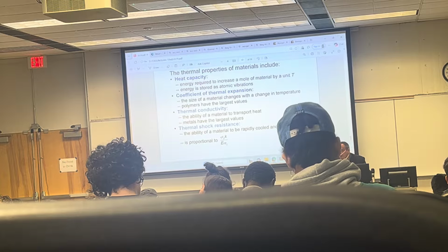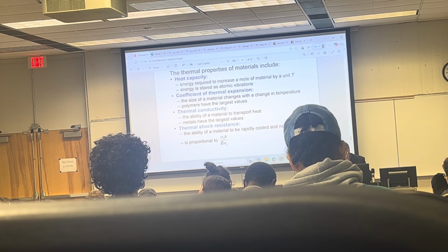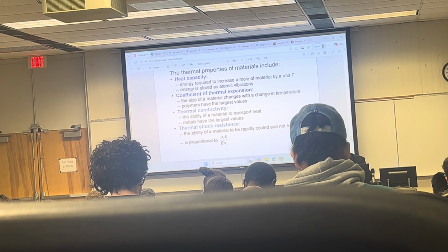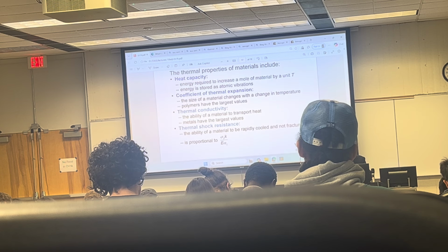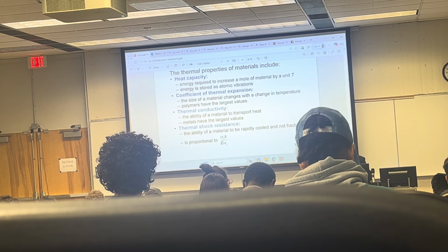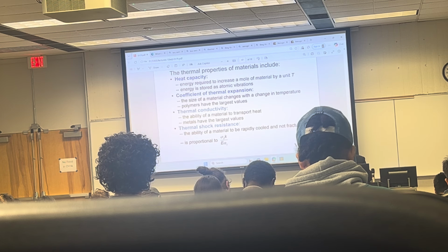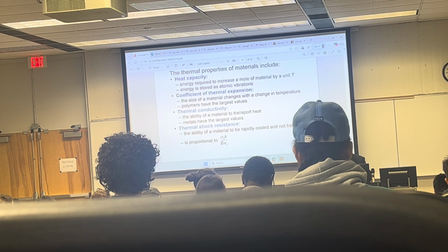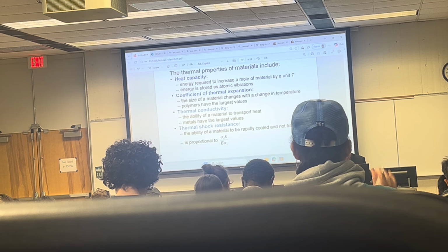Solidification happens by nucleation and growth, right? If the nucleus is less than a certain diameter, it's going to get redissolved due to the surface energy trying to collapse it, or it will grow due to the decrease of the internal energy. There's an equation that balances the two. So figure out what equation.